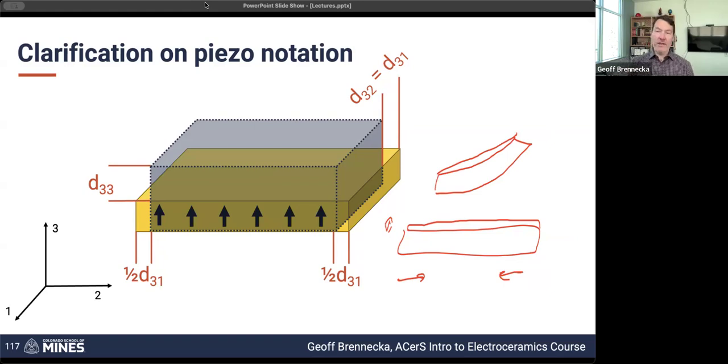So that doesn't necessarily have to be a thin film. You can do the same thing with little blocks of piezos on top of a larger membrane, or a lot of different options like that. But it's a mechanism for increasing that strain, because while I've drawn the d33 relatively large on here from a cartoon perspective, keep in mind that most of these coefficients are in the picometers per volt. So that's really, really tiny direct strain, but the force is very large. So you can bend other things around it and enhance that level of strain if that's what you're after.